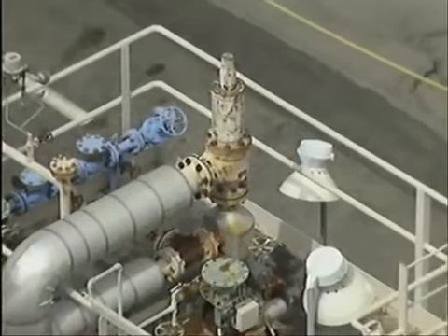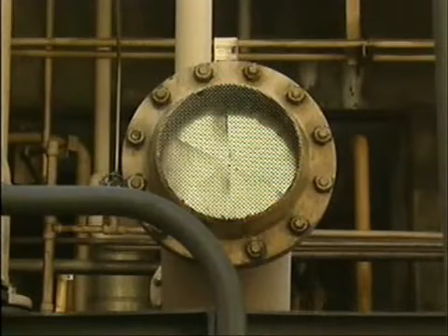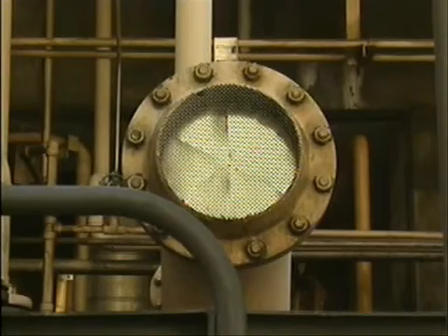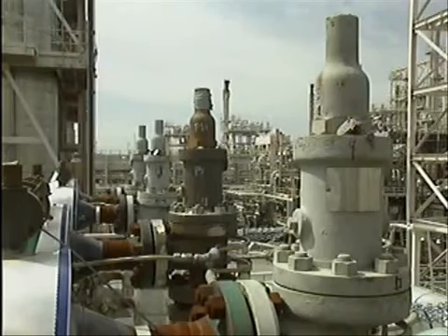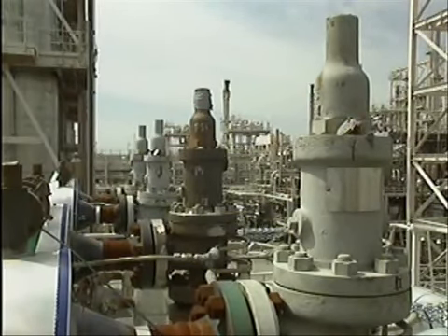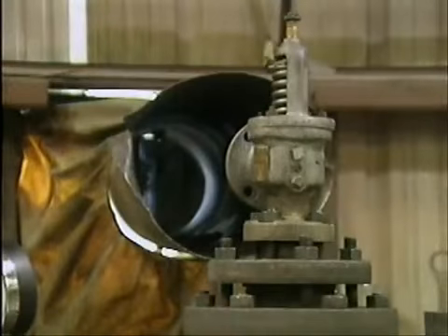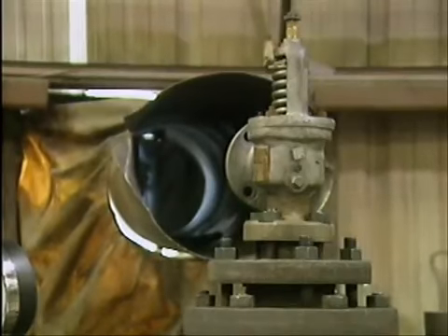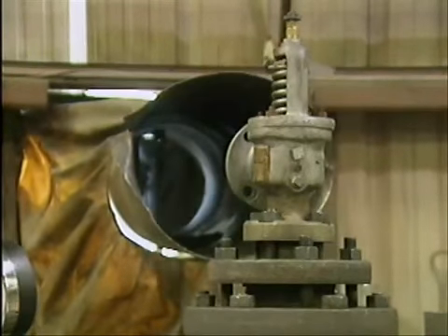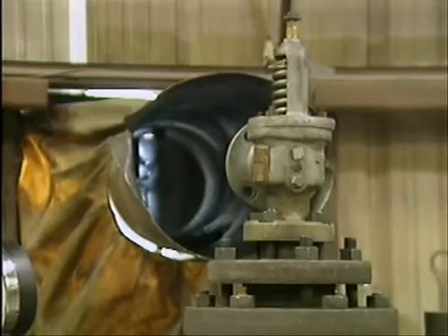Various devices are used for this purpose. Rupture discs are often used in systems where problems with excess pressure are relatively unlikely. Relief valves, which open gradually, are primarily used in systems that handle pressurized liquids. In gas or steam systems, however, safety valves are used. They're able to quickly let out large volumes of gas or steam to relieve excess pressure in the systems.